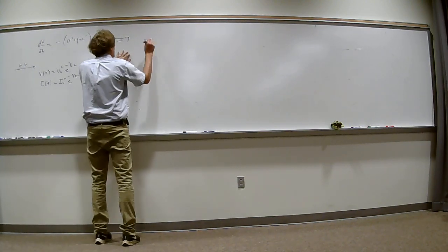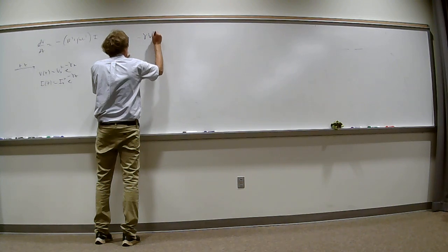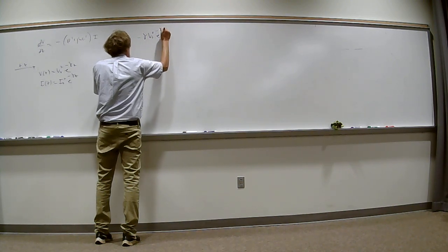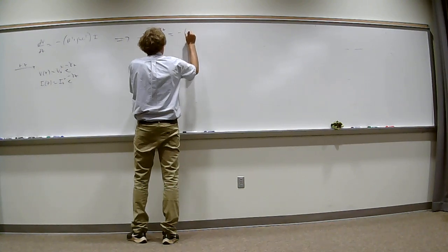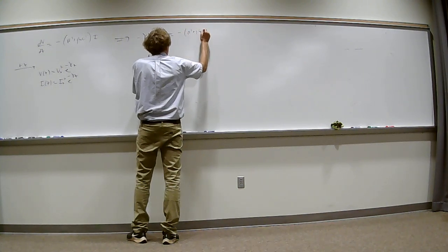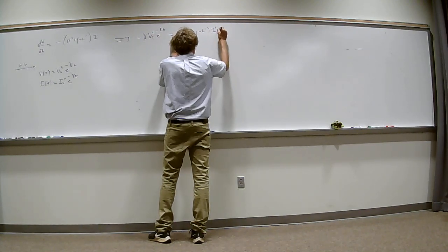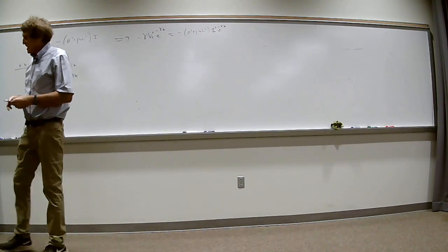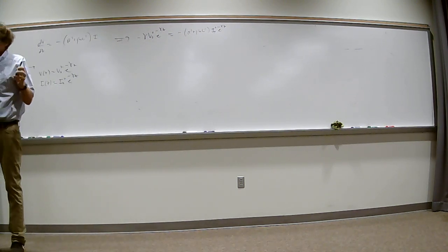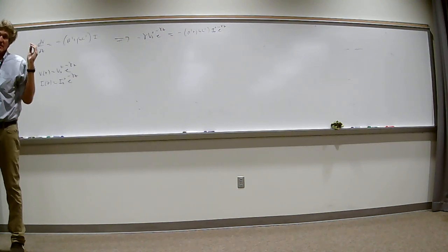So here I get minus gamma V0+ e to the minus gamma z, and that would be equal to minus (R' plus j omega L') times I. I is equal to I0+ e to the minus gamma z. Please just take a look. Make sure you see this. There's nothing I'm doing that's in any way tricky. I'm just doing the derivative, and going ahead and putting in the values I put down here for I and V into that equation.